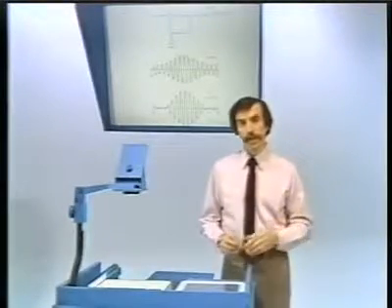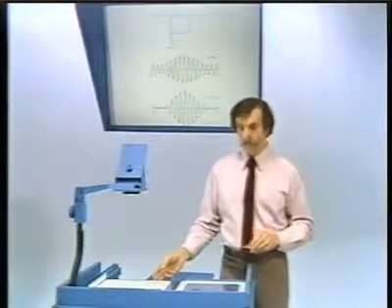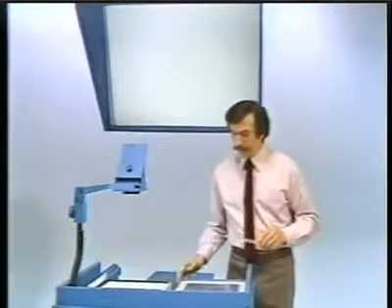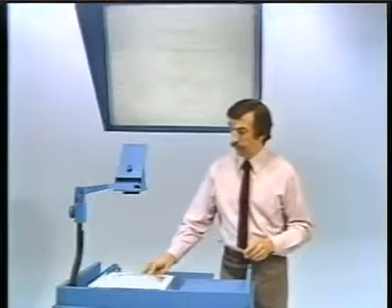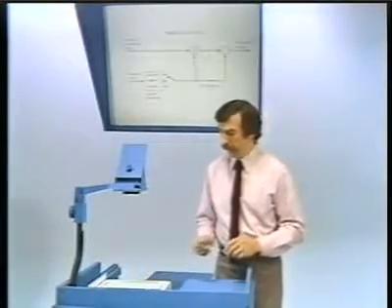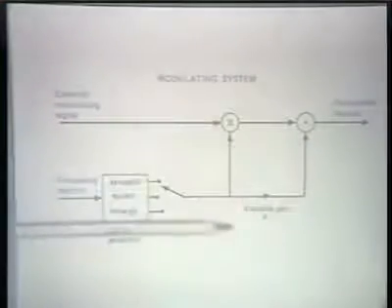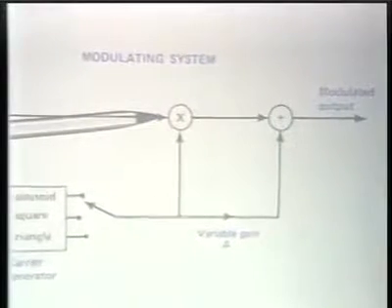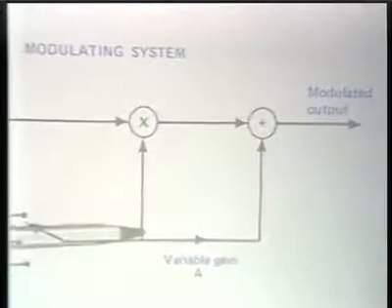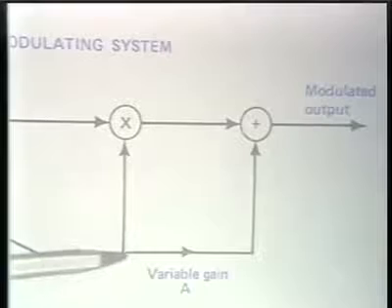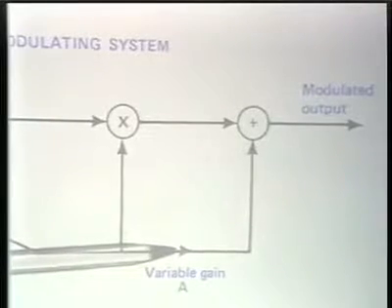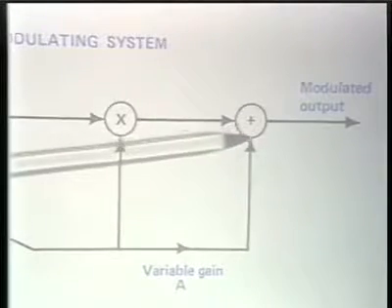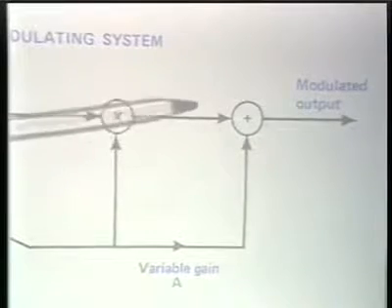Well, the modulating system that we're using in this demonstration is basically of the form that we're indicating here, and a simple block diagram for it is more or less identical to what we just saw. Specifically, the modulating signal is multiplied by the carrier, and there also is the capability of injecting some additional carrier, meaning adding it to the output of this product.